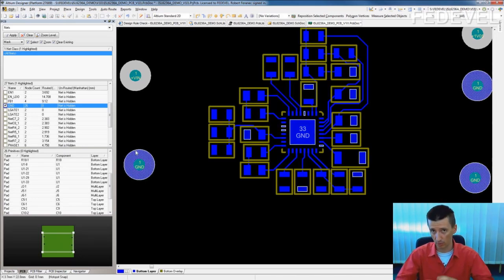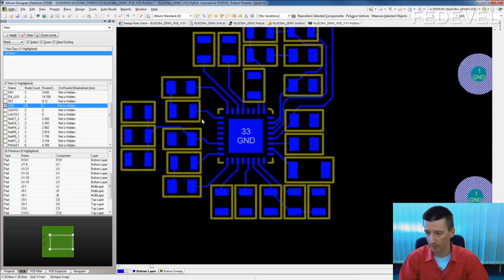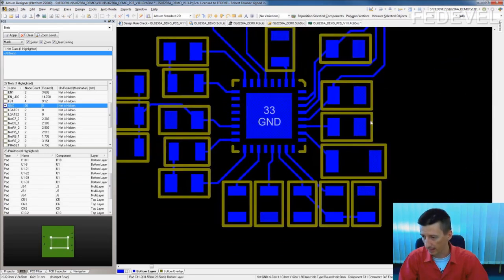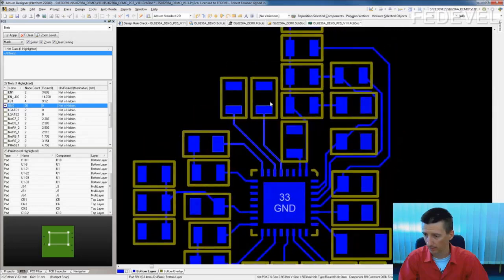You can switch on the color override, or with F5 it will disappear. So for example, if you select color for more nets, you can switch it off or switch it on with F5 if you would like to see it. You would like to see what paths are ground. Okay.